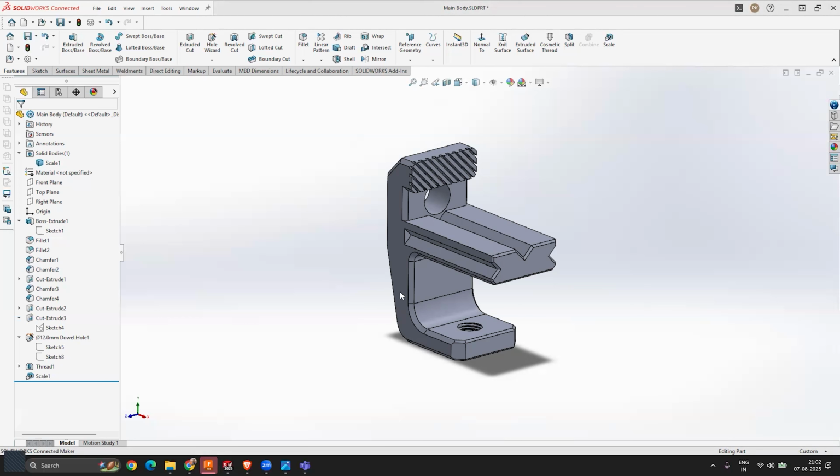Yeah. Otherwise, it's super tough to change all the dimensions by 1.2. You will have lots of errors in your drawing. If you change the first sketch, the rest of the features will start showing errors, and that will be super complex if you have multiple parts or assemblies. So the best way is always to use the Scale command.